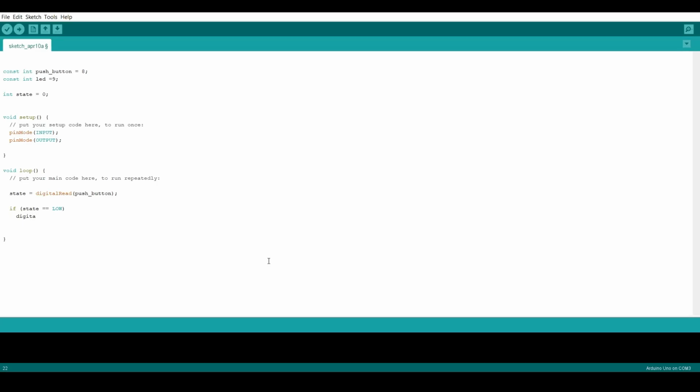So we want to write on the pin of the LED. We want to write HIGH. You can write LOW too. You can test it out however it feels for you guys, but just to show you how it works. digitalWrite LED, that's the pin we're choosing to turn on, so I'm going to put HIGH here.